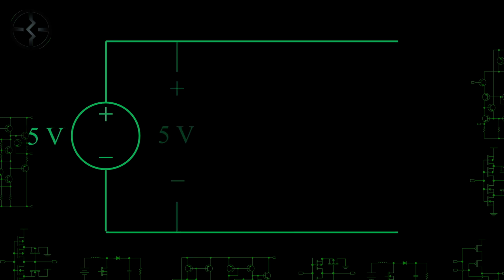On the left is an ideal voltage source symbol, and it indicates that there is a defined voltage between the top and bottom of the symbol. Let's give that a number for easy reference. It doesn't matter where you measure in this circuit, there will always be 5 volts between the top and bottom wires. If you have a conductor and you apply a voltage across it, you will get some current flowing through it. However, in the circuit shown, we have an open circuit, so there's no current flowing.